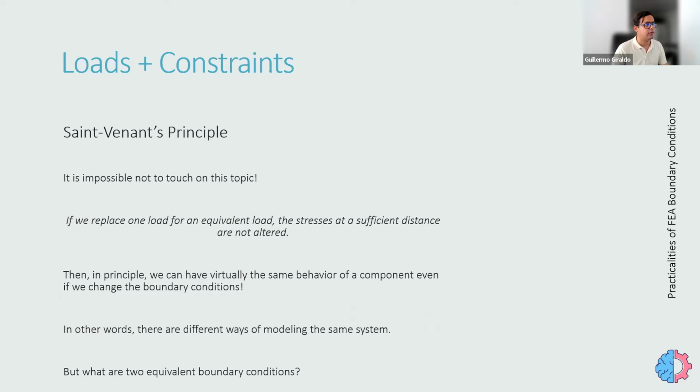So some are forces, or loads that can be converted into forces, like body forces or pressures, thermal loading, etc. And the other are constraints, which are only the degrees of freedom or the displacement that we prescribe. So it can be displacements that are constrained to zero, or that have some non-zero predefined value. So these are loads and constraints. So how they relate, and what I think is a very good engineering approach into thinking about loads and constraints.